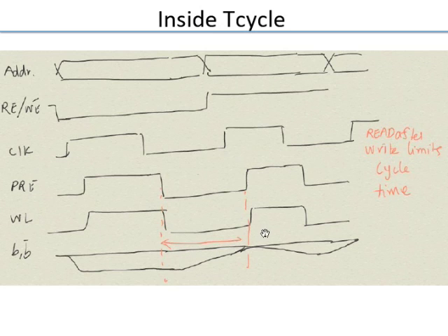So the time required to do this usually limits the cycle time, because these are large capacitances, and again you can't have very large pre-charge transistors, because everything is constrained by area. So that limits the cycle time.